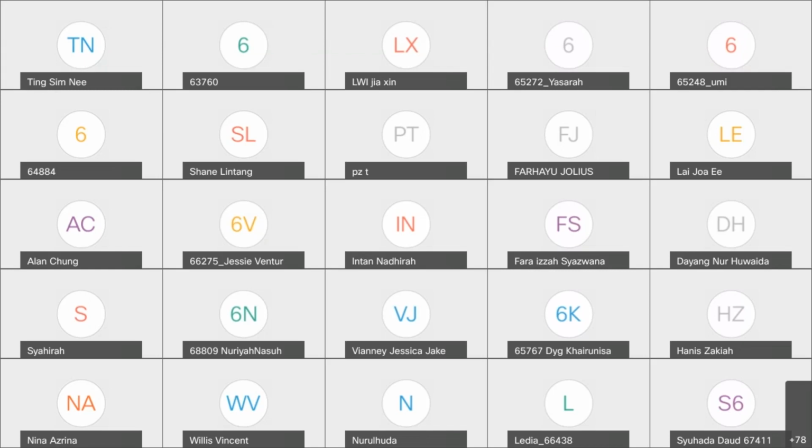But, you see, the formula is production rate is quantity of work over time. So if you want to calculate time and you don't have quantity, how are you going to calculate? You understand, right? Yes, Doctor. Paham. So you need the material first so that you can play with your production rate formula. Otherwise, your production rate formula will have two unknowns, time and quantity, correct or not? Even if you have a production rate, how are you going to find the time, because you don't have the quantity? So quantity comes from the material. Quantity, resources, data sheet of material.